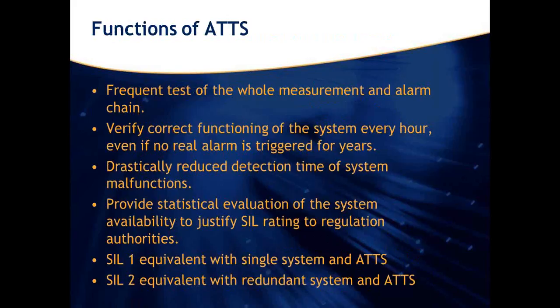This is what is called the proven by experience approach. In general, when a SIL 1 level is required, a single system with an ATTS is a suitable configuration, and when SIL 2 level is required, then we need a redundant system with a redundant ATTS and the voting system.